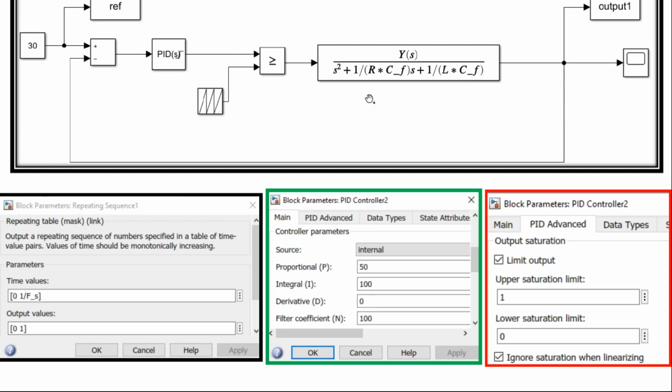If you remove these, the auto tuning will work perfectly. Due to these two non-linear elements, the auto tuning is not working. However, remove them and try to get some values, then place these two elements back and do the manual tuning. The first tuning value you can take from the auto tuning you got without these two blocks. Okay.